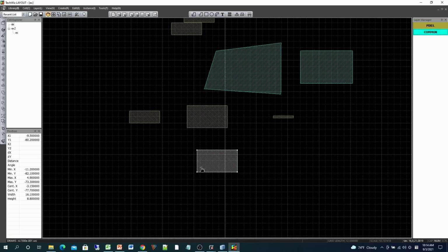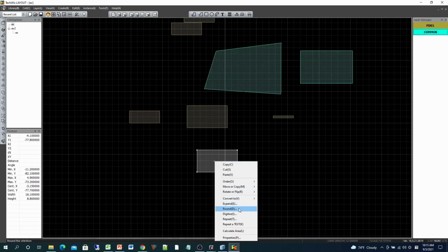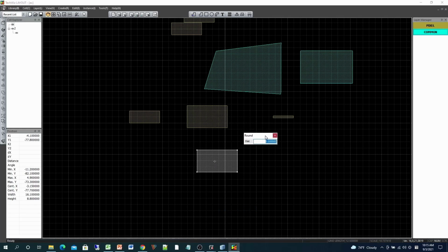And the following option is the round option. To make the mask rounded, new nodes are added to both sides of a node in the corner at a user-defined distance. So the existing node is removed. As an example, I will click the round option and then I will enter the distance as 1. So you can see that it changes the polygon shape to be more rounded.